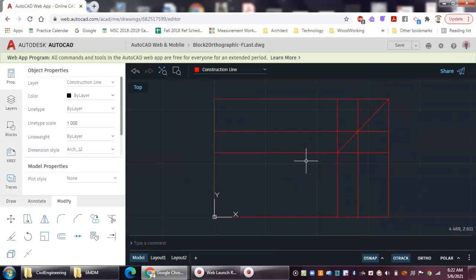All right, so there's our 9 lines set up like we had before. Only there's a difference now as far as our 9 lines, because in that front view, remember this is kind of like the L-shaped block where this corner of that block is cut out. So we need to place some construction lines there so we know where we should put those object lines in each view. So I'm going to go back to my offset.